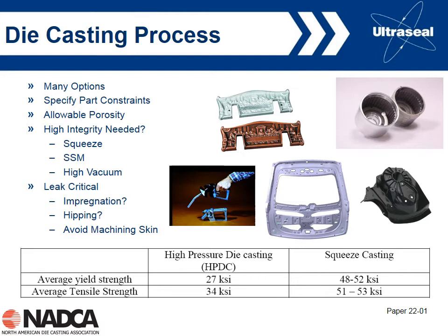And so the point is that it's very difficult to change in mid-stride. If you design the die for conventional die casting, it's very difficult to change it to high vacuum die casting or squeeze casting. So you really need to think up front which process am I going to use it for? Very difficult to change in midstream if you're not producing the required quality with whatever process you initially chose.